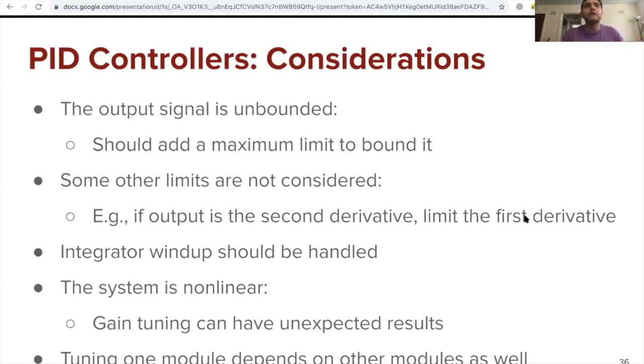As a result, the next time you change your yaw, you have a very large error in I that needs to be dealt with. Otherwise, it will not let you go to the new point. It's called integrator windup. You need to handle it.